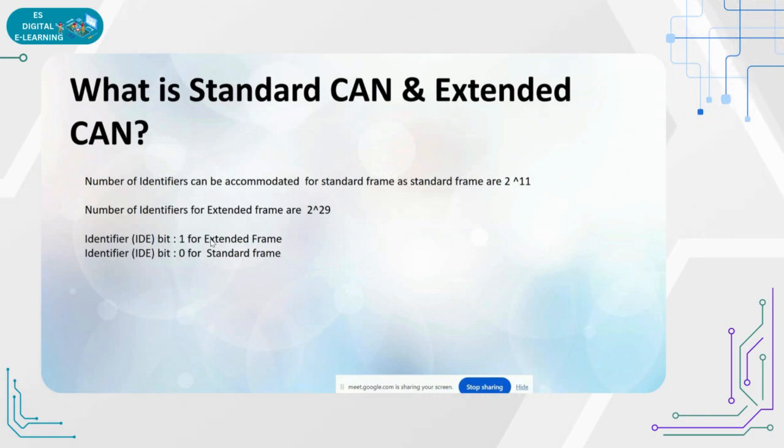What is a standard and extended? Standard is an 11-bit identifier, extended is a 29-bit identifier. Okay, so what is the main difference? In the frames, we have the IDE bit. IDE bit 1 means it is the extended frame and 0 means standard frame.